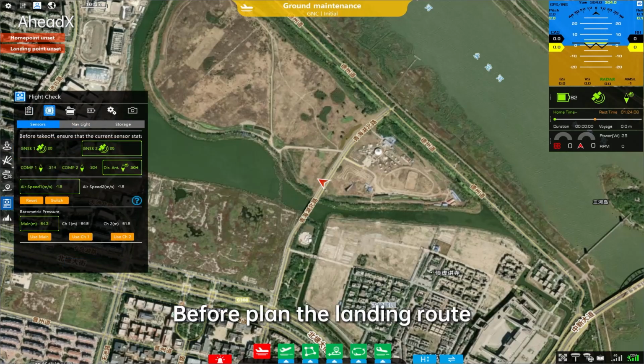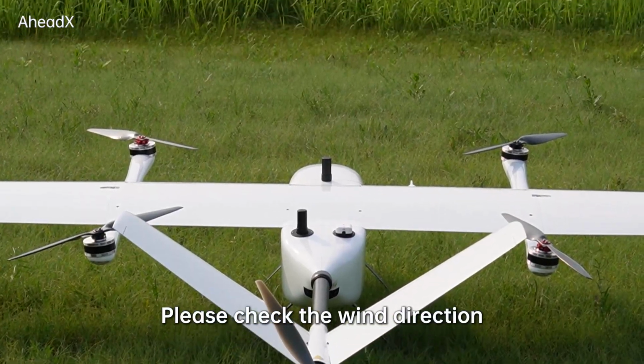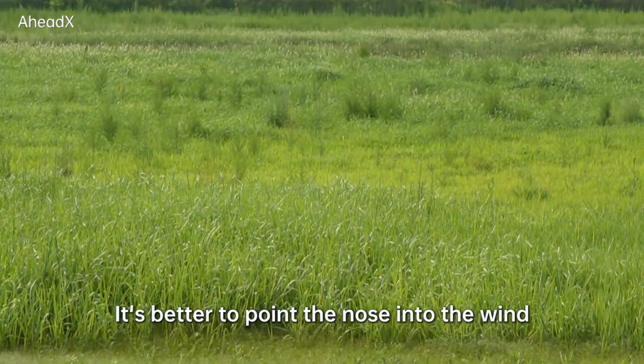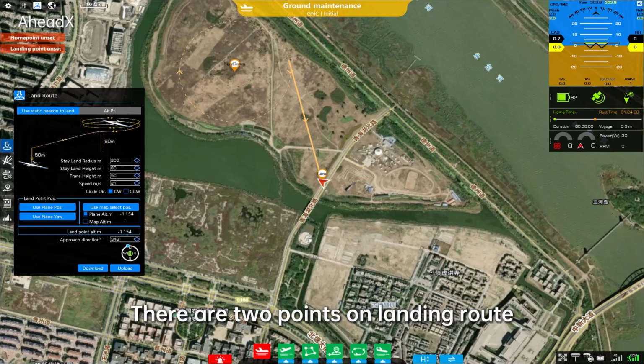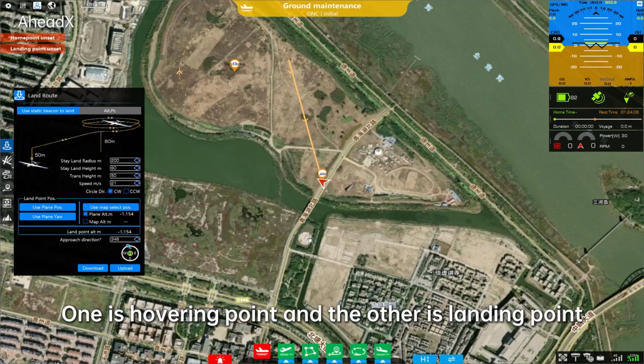Before planning the landing route, please check the wind direction. It's better to point the nose into the wind. Click Land Route Panel button. Use static beacon to land. There are 2 points on landing route. One is hovering point and the other is landing point.